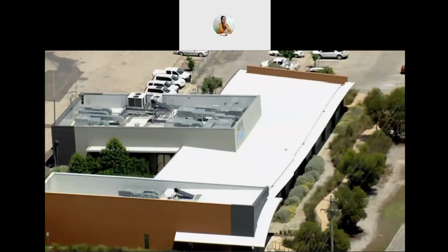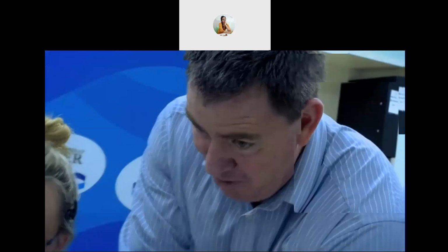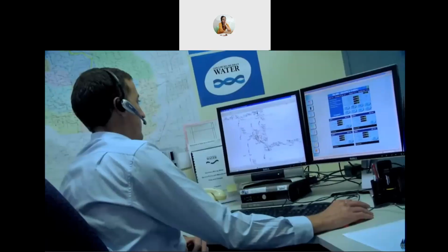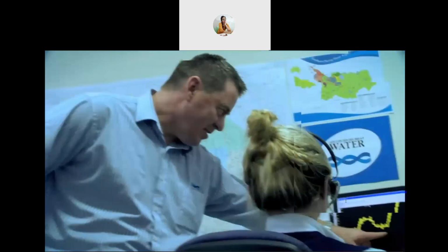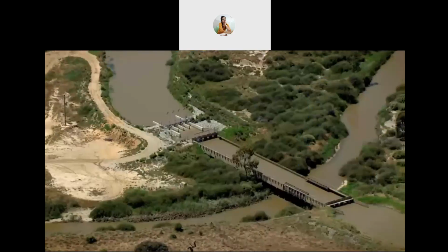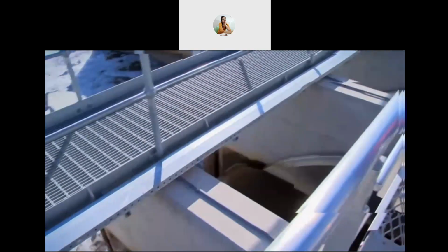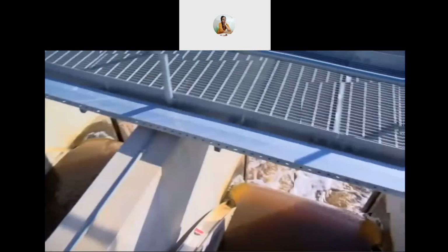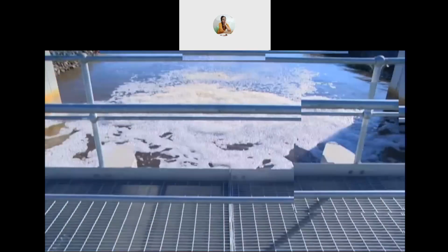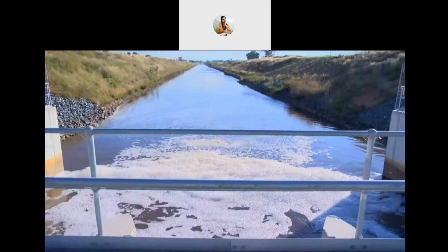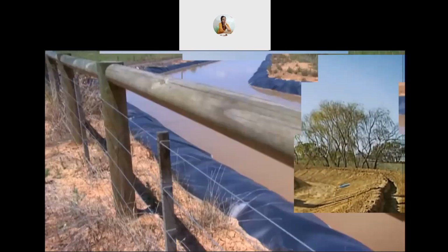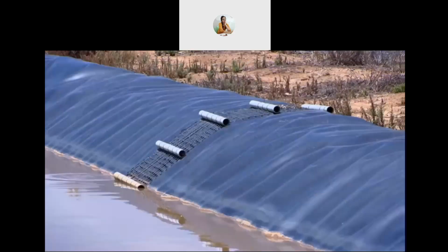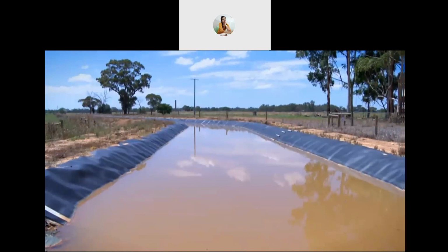The entire network is centrally managed using software which automates every aspect of the operation: customer ordering, planning and scheduling, automatically controlling the farmer's outlet, and customer usage and entitlement reporting. Networks of flume gates precisely measure and control the flow of water, constantly adjusting to ensure optimal system operation. Human intervention is only required to address any problems that are identified by comprehensive diagnostics. And through accurate measurement, the system is able to identify high-loss sections of canal for targeted remediation, ensuring limited maintenance resources can be spent to achieve maximum benefit.